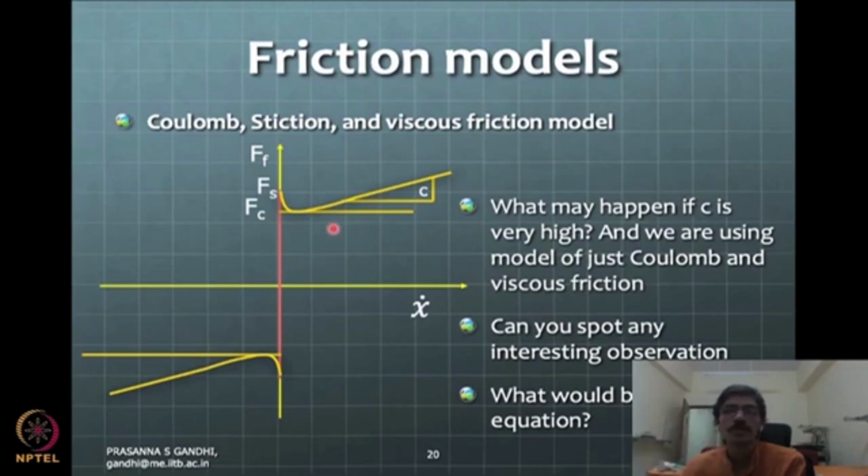If you are always using the motor at a little bit higher speeds, you are not bothered about this part at all. You are not stopping and starting the motor multiple times, and you are not interested in very fine positioning. If you have a positioning system you will definitely stop, but if you are not interested in fine positioning, then you don't worry about this part. You leave this part to your integrator module to handle, if at all.